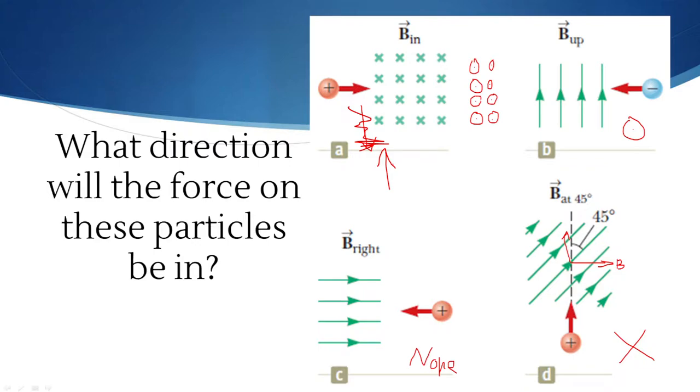Okay, so getting right-hand rules right for this takes a little bit of practice because it is very strange. Having to keep track of it in this way is something that you haven't really done before, and frankly, it's something that I, out of practice, can still make mistakes on. So, as a reminder for the right-hand rule, you hold your hand open, kind of like an L. Your fingertips point in the direction of current. Your palm points in the direction the magnetic field points, and as a result, your thumb will point in the direction that the force is in.